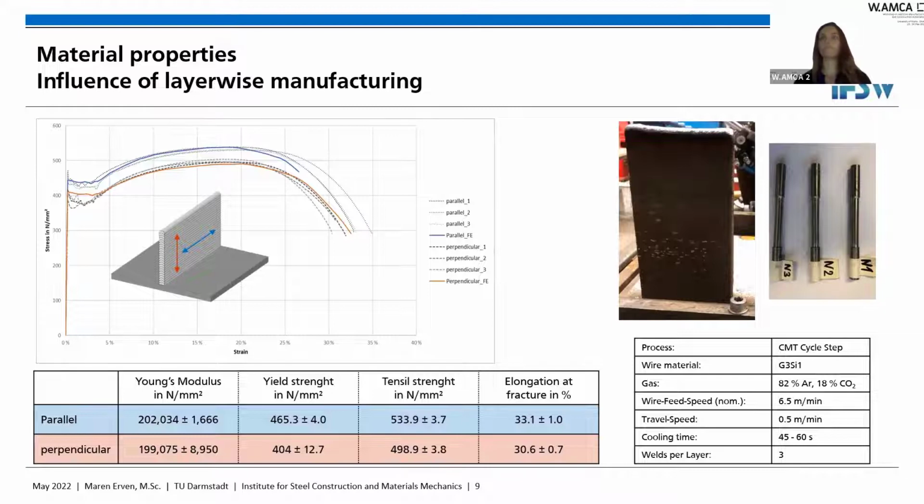Do you have a hypothesis for the origin of this anisotropy, like the micromechanical reason for the anisotropic effect here? Not yet, but I want to focus on that, because there is some research about stainless steel, where there is a high anisotropy inside when you print it, and there are also some reasons for that, but I'm not sure how I can transfer it to this. But anyway, the anisotropy could be that the layers are not connected so well, because there's not enough energy.